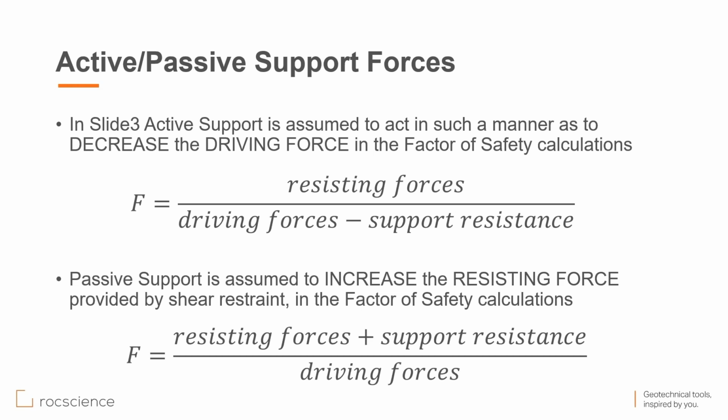There's a lot of debate on this topic on what you should use with what support. Basically, it's up to you. Typically, we would say something like, for a grouted tieback, because the force of the support is applied before movement occurs, then you subtract it before the driving forces, for example, but it's up to you.